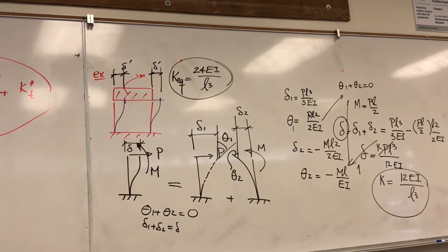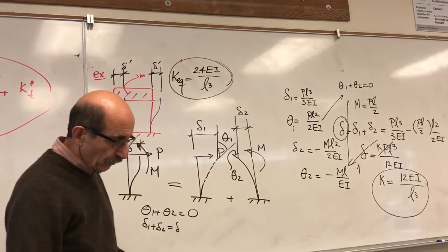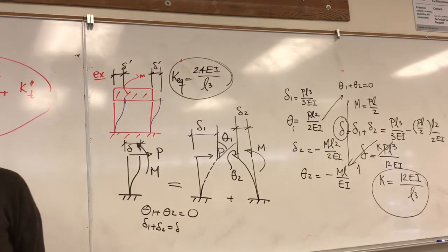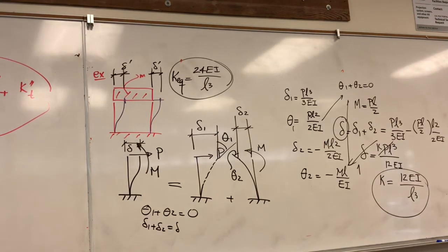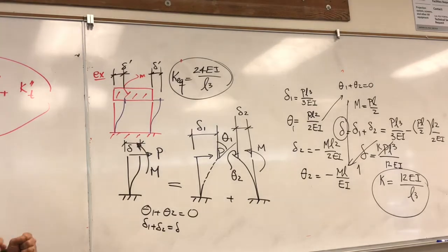That's another thing that you may want to remember. As I said, this structural analysis is a very broad approach. You can utilize all your knowledge from statics and strength of materials to just try to relate the stiffness to displacement. That's the objective. So you use all those methods, but also remember the concept of series and parallel for spring summation.